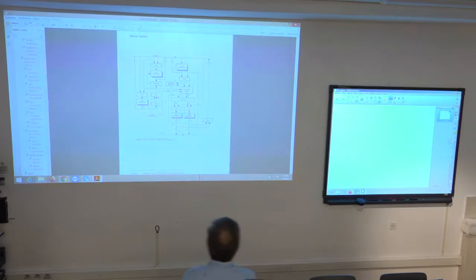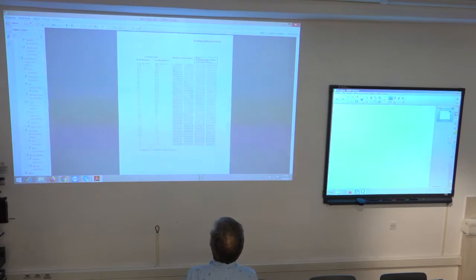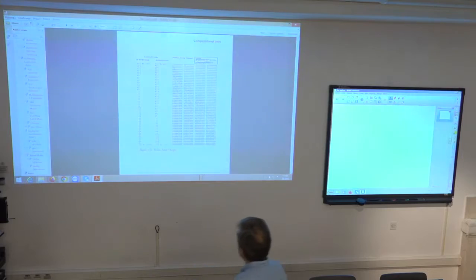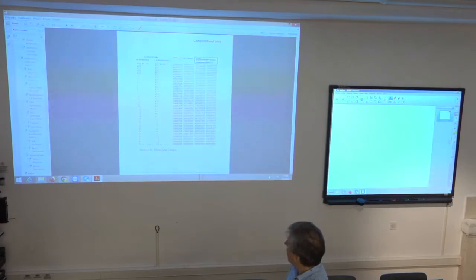You have here several examples of what happens for arithmetic shift and for logical shift, and it describes two cases: shift left or right relative to the upper word (high reference), or shift left or right relative to the lower word (low reference). In this case, the input value was ABC and so on. This value is then shifted to each possible position in the output register, based on the input value that is either in this SE register or given as a constant in the instruction.